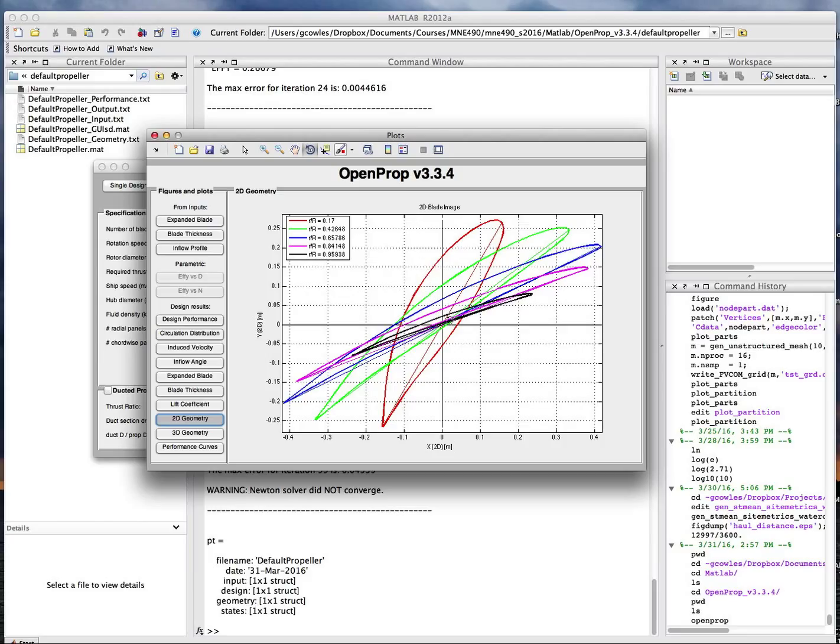So if I put a lift vector on here, it points mostly in the direction of wanting to travel, a thrust direction which is up the screen, and a little bit to the left, which is counter to the direction it's rotating, which is basically like a drag term in terms of the torque. So you can see how that variation occurs here, and really how very important these last components are. So it is quite striking, the thickness distribution variation in this propeller.